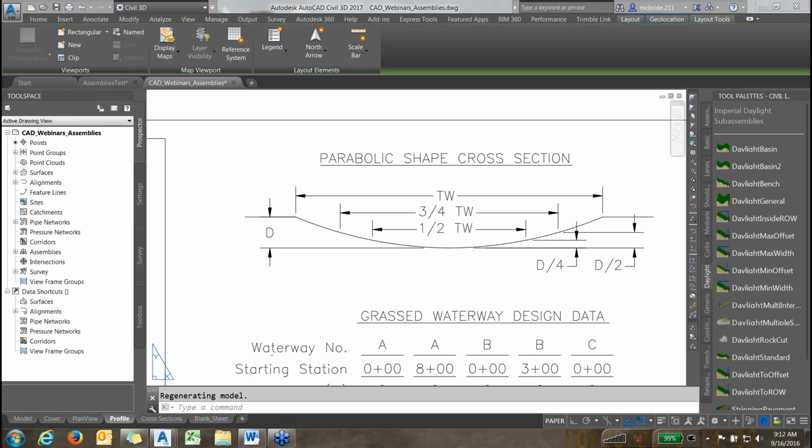So you would have to come out maybe a flat distance of 5 feet, then do your down slope, your bottom, your up slope, and then daylight it. So yes, you could do something like that and have the whole thing offset. It doesn't necessarily need to be centered, but for most of our waterways and open ditch type projects, it's probably the easiest way to do it because we're designing to a low bank. In that case, you wouldn't be designing to a low bank. One bank would be fixed. So yes, you could do that.